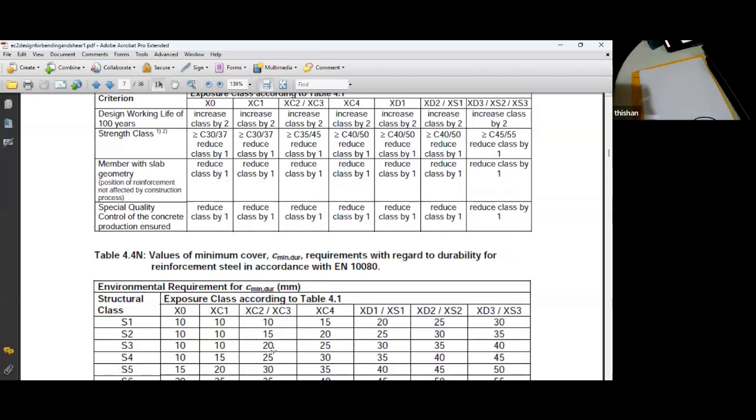So if you are using concrete like 45 or 50 megapascal cube strength, the cover requirement is 30, otherwise 35. It's a simple number to remember. Cover requirement is 35, whatever it is, because we are not going to use 50 megapascal concrete for slabs and beams, it's useless. 50 megapascal is needed only for columns. So you don't have to do anything like that.